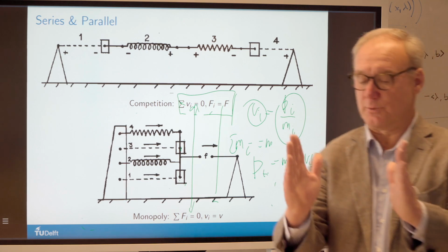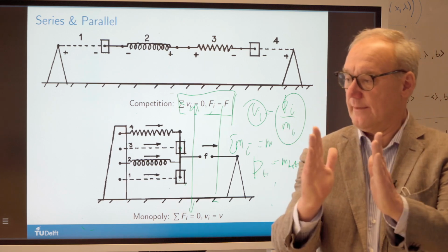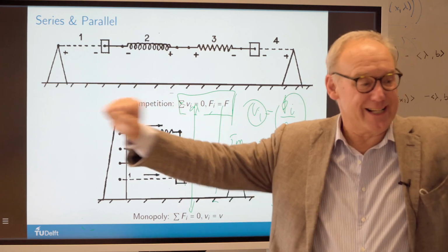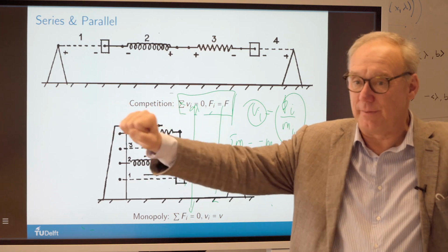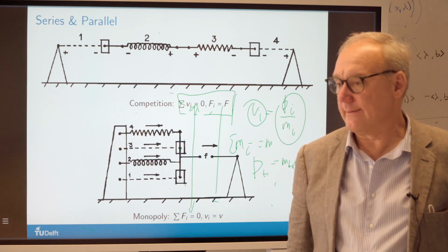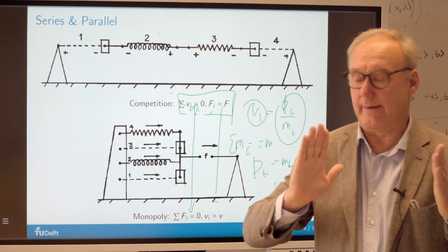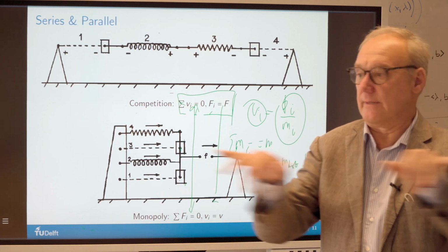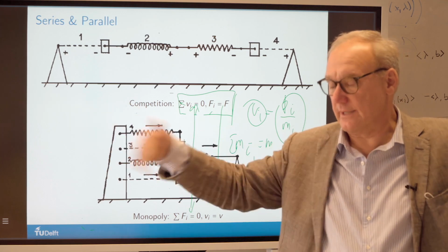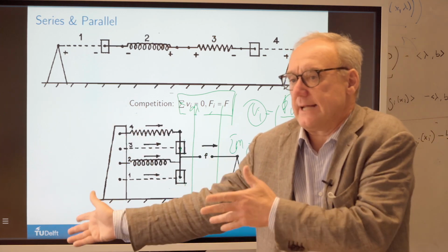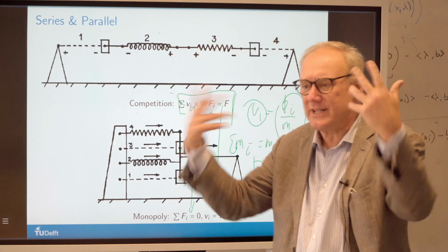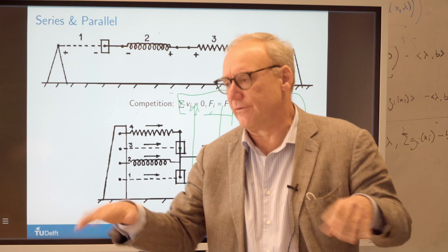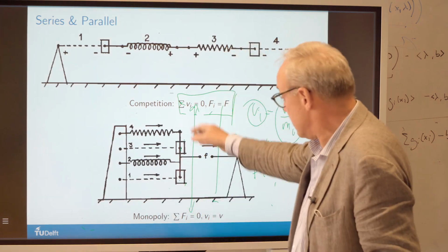Yeah, so you put 2 springs in parallel, it gets twice as stiff. You put them in series, it becomes 1 over the total, and I think that's much more floppy, huh? But much more elastic, right? You put 2 dampers in parallel, of course it's going to, huh? You put them in series, it's going to be much easier, right? So you get the 1 over law. It's the same with masses. It's not easy enough to imagine. You want to accelerate 2 masses in series, okay, you get the 1 over law, and then you want them in parallel, well, it's the plus law.